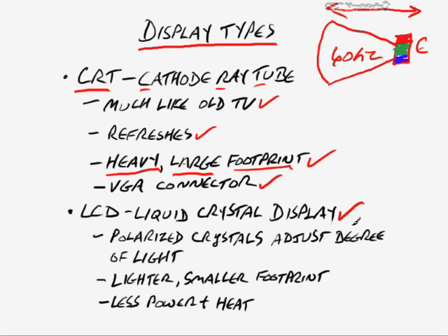What happens with this is that it uses polarization, and it does this through two filters. One filter will block all of the light waves. It works at a right angle to block those waves. And then there's a second polarizing filter, which is actually the liquid crystal display part of this. And these things will flow like liquid, but they're actually little crystals, and they will focus to each pixel in the screen. Each pixel is again composed of red, green, and blue. And so, for example, here you might see each pixel with some combination of red, green, and blue in it.